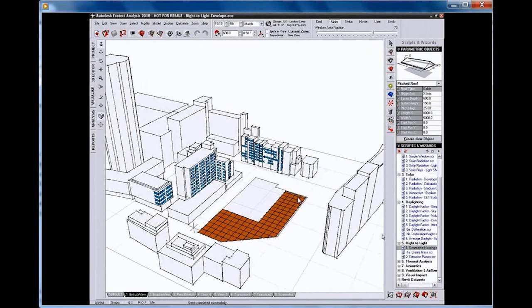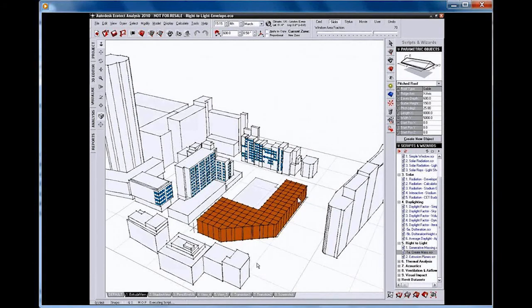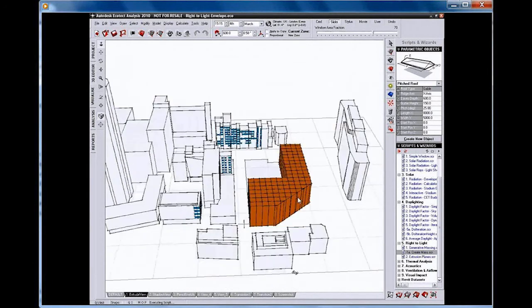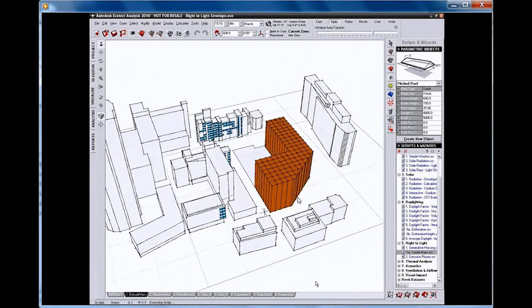Different alternative, here we can use a slide bar and actually get the software to design the overall envelope of the building, to guarantee that we're not taking light away from the neighbouring windows. So in this case we're using analysis to actually drive the design. The software is automatically determining the outer shape of the building so that we're not robbing light from the neighbouring windows.